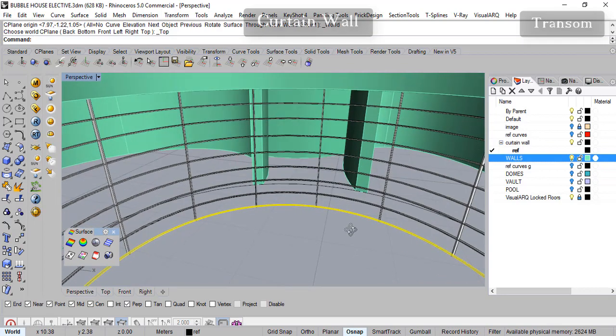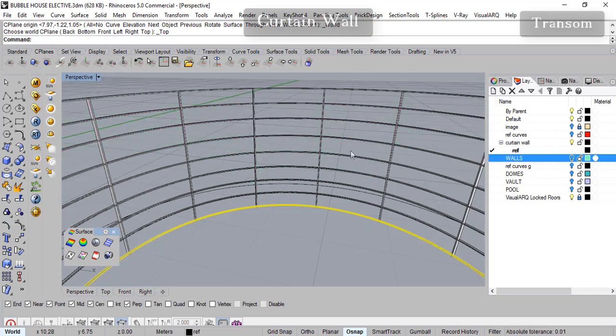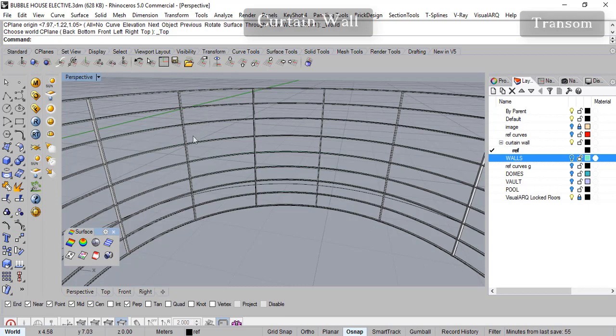So we can do it, we'll just put out the walls layer, and these are the two ones we need to cut away. So we use the simple split option, we use this as the cutting object and we cut away these portions. But we will not use this plate, because then we'll create voids in between these members. So we want the splits to happen in such a way that all of the members are left solid.